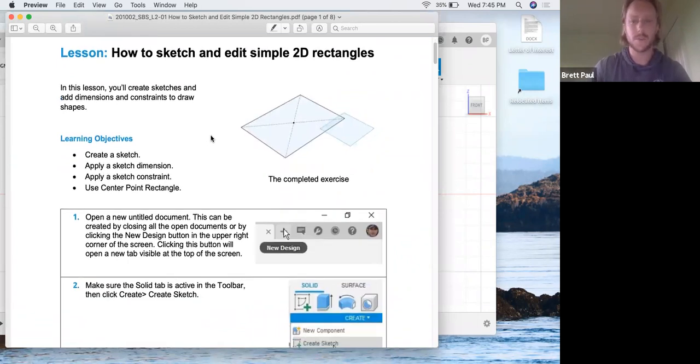in this tutorial, we are going to learn how to create a sketch. Sketches are kind of the basis for how you model. So you make two-dimensional sketches, and once those are fully dimensioned and fully constrained, therefore the geometry is fully defined, you'll finish the sketch and then you can extrude it using a variety of tools to create the third dimension.